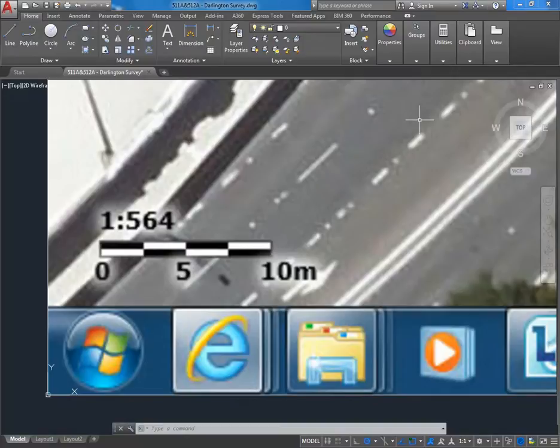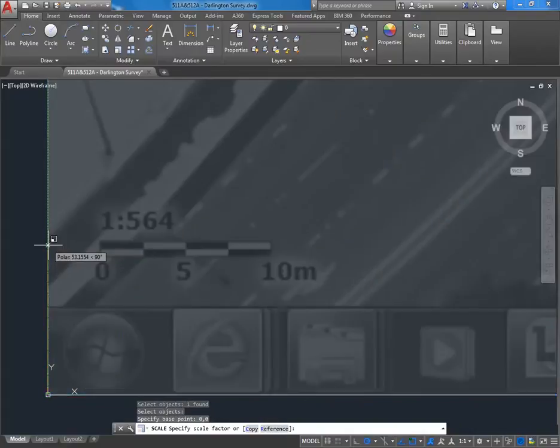And the answer is use that scale factor that I just showed you. So I'll go back to scale, repeating the process, selecting the border, enter, 0, 0 for the base point. So again, that means it'll scale from the corner here. Now again, it's asking me for the scale factor. So the way that we can enter those measurements is to put in the size we want it to be, 10,000 millimetres, 10 metres, so 10,000 / the actual size, 63. And that formula will work in any situation.